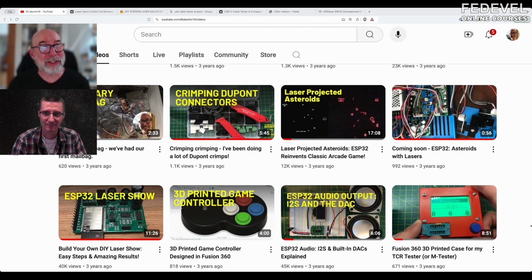I think often the worry that something's not going to work is sometimes overstated, and often you know quite quickly if something's not going to work because you can iterate. Can I try it out on a dev board first? Do I do it on a breadboard? Play around, try all the different components that I'm trying to use together. Do they all work individually? Can I write the code to talk to them all individually? And then you can start bringing together the bigger project of all the bits you've already prototyped and know work.